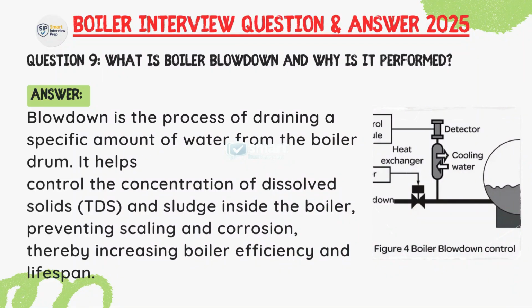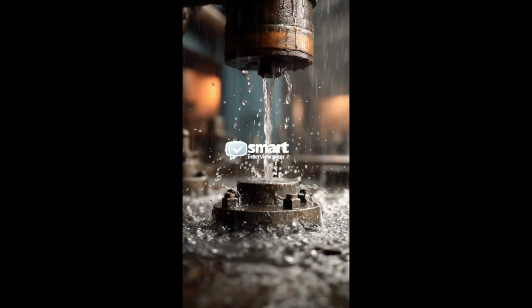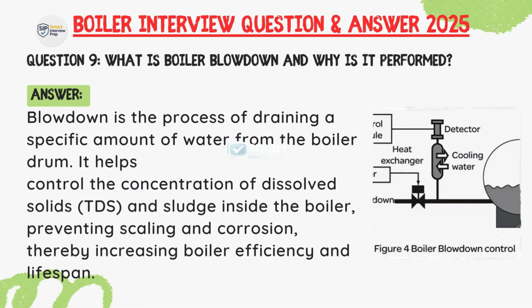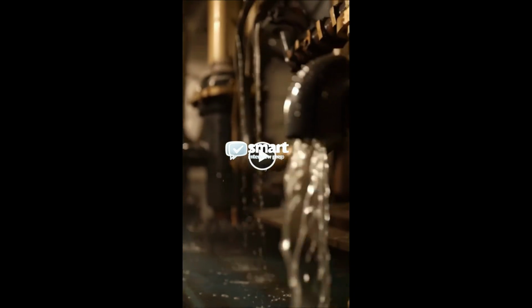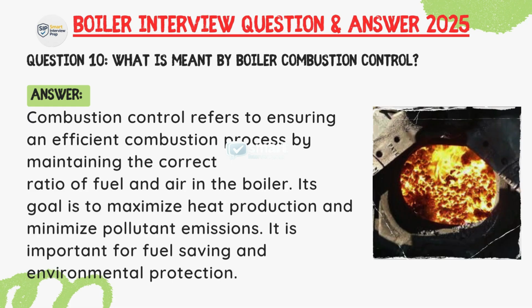Question: what is boiler blowdown and why is it performed? Answer: blowdown is the process of draining a specific amount of water from the boiler drum. It helps control the concentration of dissolved solids like TDS and sludge inside the boiler, preventing scaling and corrosion, thereby increasing boiler efficiency and lifespan. Question: what is meant by boiler combustion control?